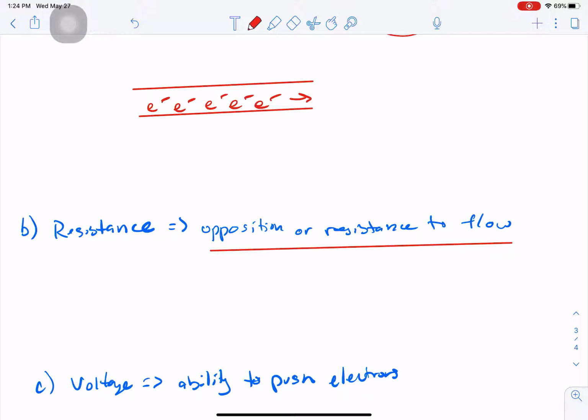Plastics are entirely different. They don't have that same crystalline structure. Their molecules are typically these long, repetitive chains. We call these polymers. And they're bonded together in such a way that the electrons inside the atom are fully occupied. In short, there are no really free electrons that can move about in plastics or these insulators to carry an electric current. This is why plastics are good insulators. They put up high resistance to electrons flowing through them.